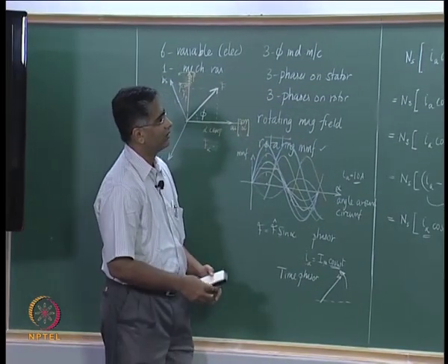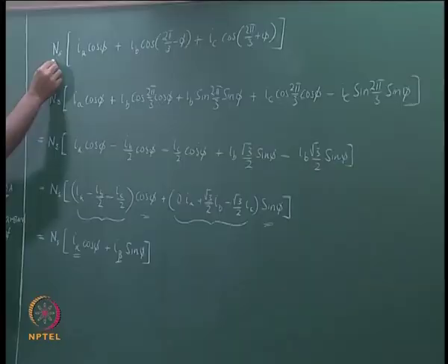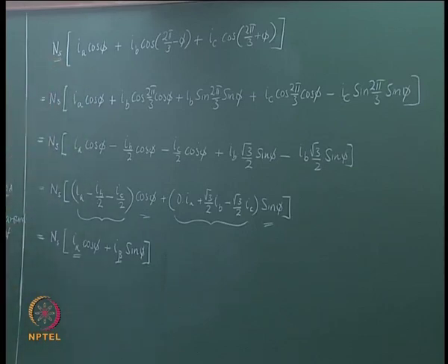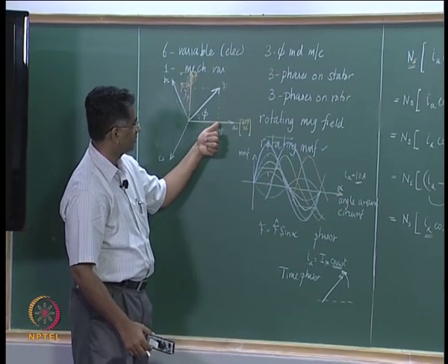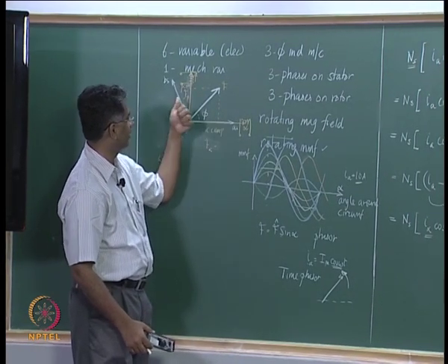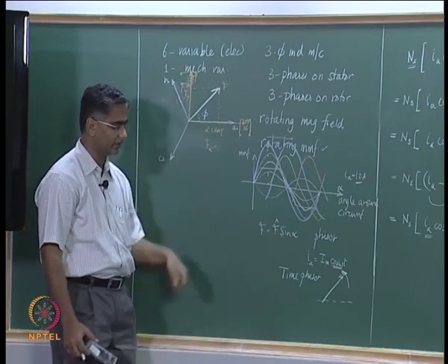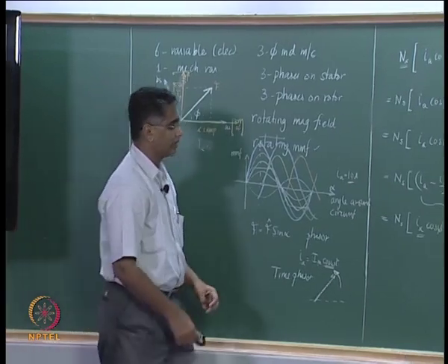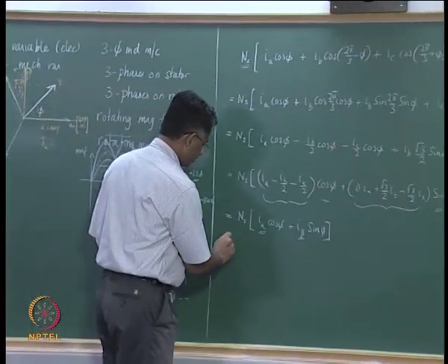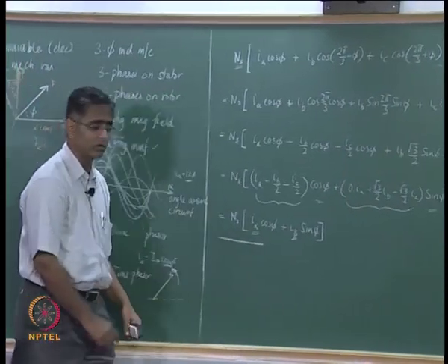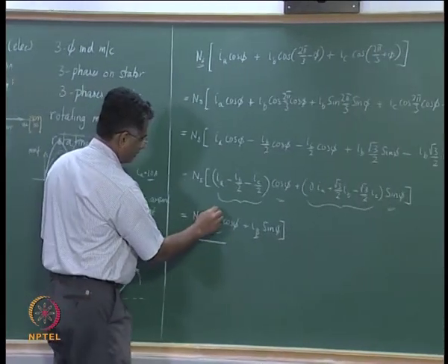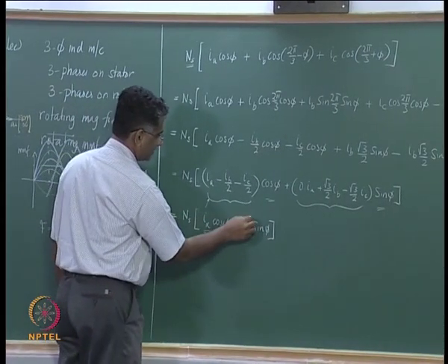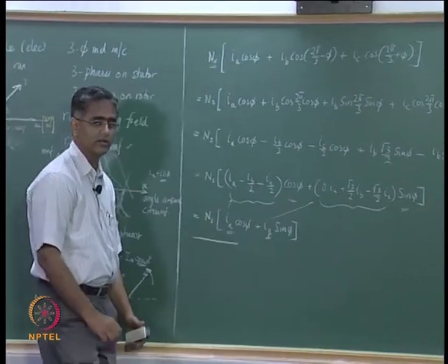Now, we have looked at this total current being the total MMF being generated by the number of turns consisting in the A phase winding, B phase winding and C phase winding. Now, we can be a little more general and say that you have I alpha as this current and I beta as this current.